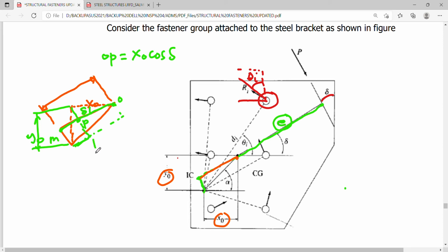Okay, so the distance PM, which is also equal to this distance here. PM there is equal to P prime M prime. Okay, such that this triangle now, which constitutes your YO, will have an angle delta here. So this angle is also delta. So if I want to get this, this is a sine. So M prime P prime is simply equal to the distance YO multiplied by the sine of the angle delta.